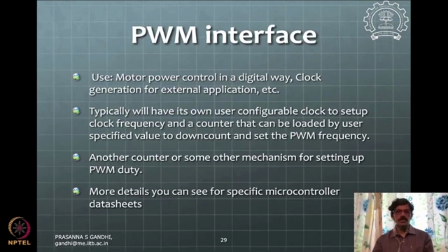With the PWM, you can have different possibilities of varying that duty, in the sense you can say this is a 10% PWM or 10% duty PWM, where the on time can be changed depending upon the application or the requirement. So this PWM interface provides a facility to change the frequency and on time of the pulse. The more programming details will be in the microcontroller datasheet, and we'll have a look at them in further classes.